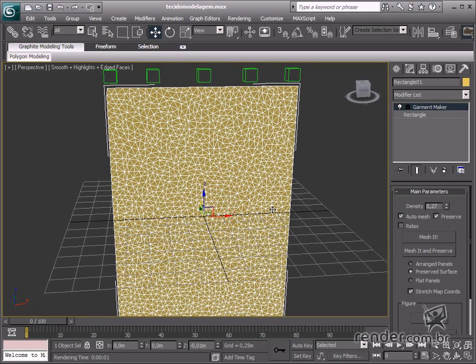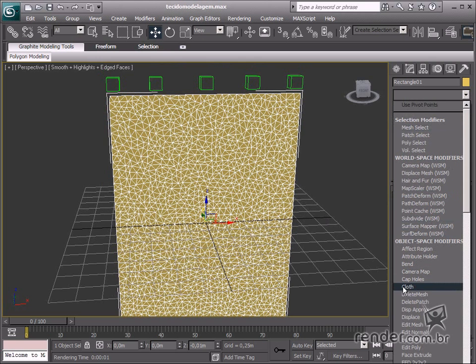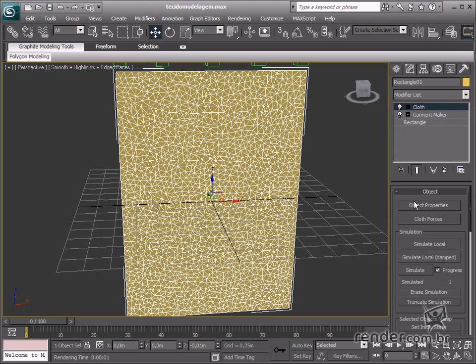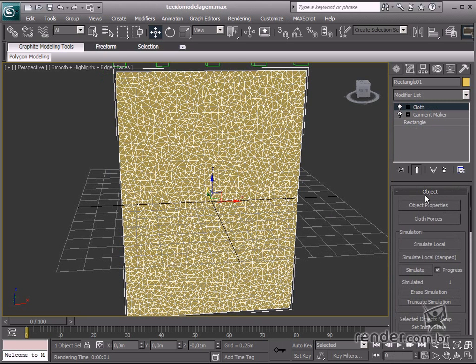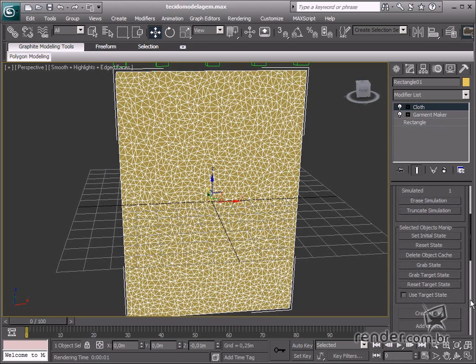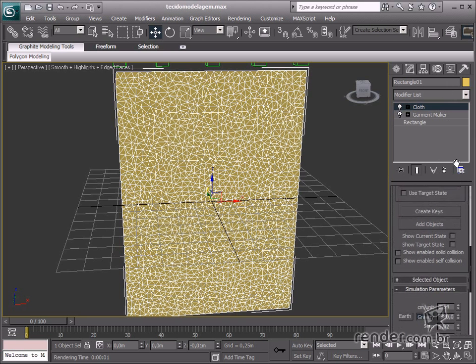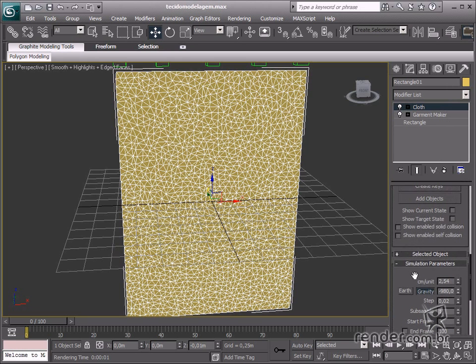Now we're going to prepare the mesh for changing into a cloth, so create references for the rings to simulate the drape pleats. Assess the list of modifiers and select the Cloth Modifier. There are several types of configurations. Some of them are Cloth Options, Simulation, and Properties. Let's enable the Self-Collision option, which will display the self-collisions of the cloth. Click Object Properties.